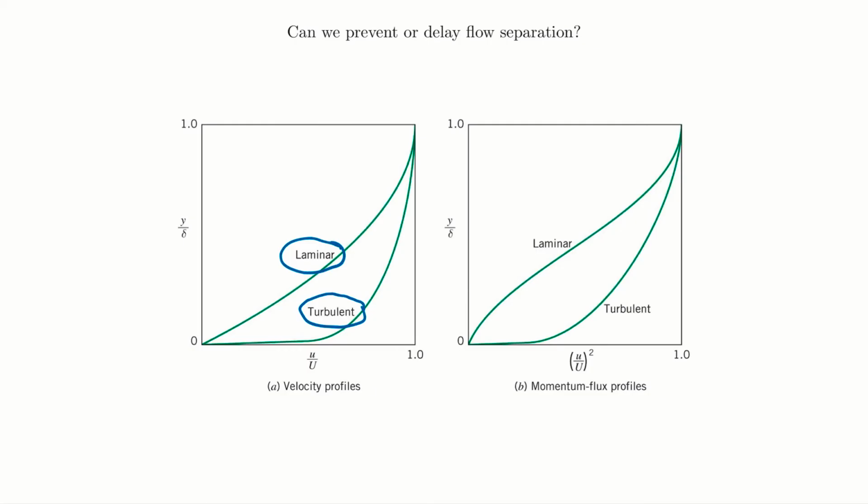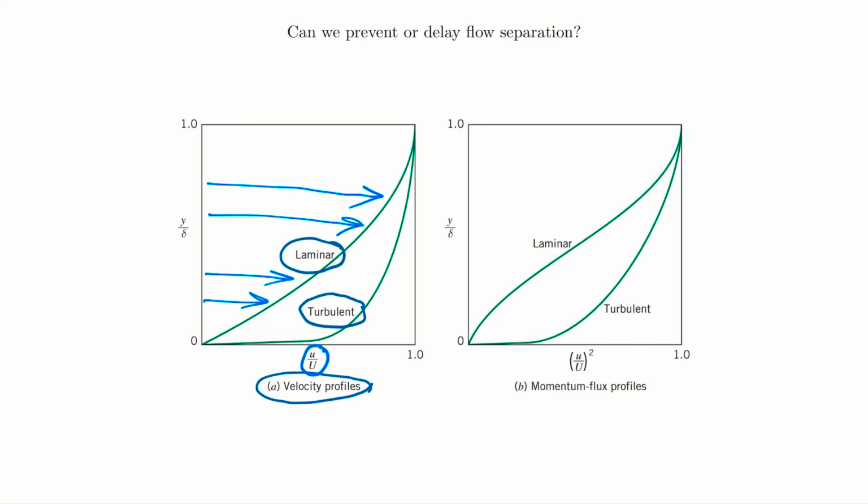So we're looking at velocity profiles here. This is plotting velocity. We oftentimes draw arrows in here. So that's the laminar one. And then this is your distance y away from the wall, where at 1.0 you're at the edge of the boundary layer, because we're scaling to the boundary layer thickness, delta. So within the boundary layer, in the laminar flow, you have a gradual difference.